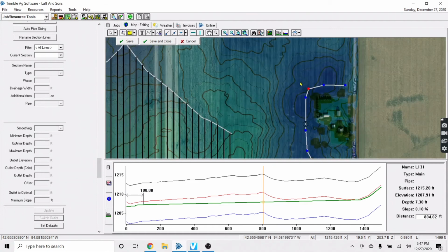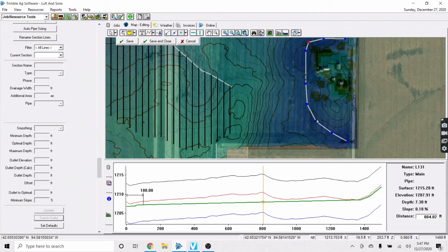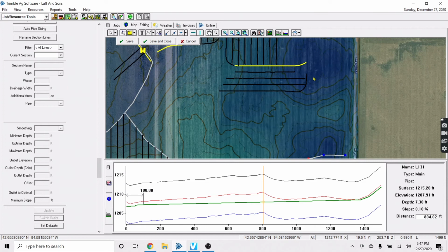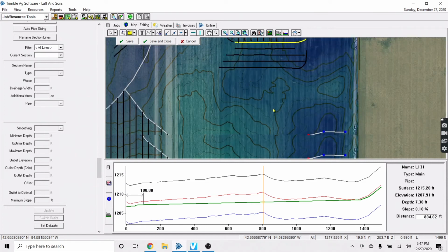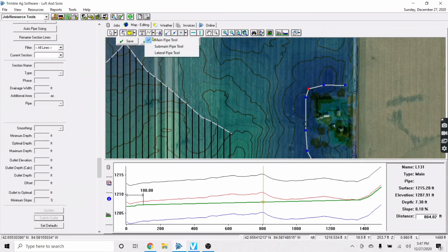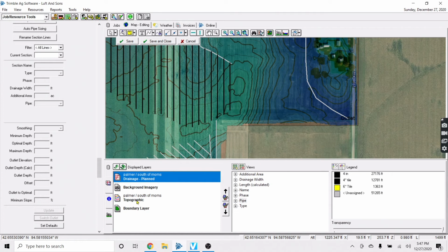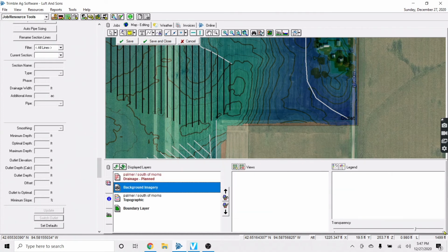Going to get 7 foot deep to get back there, which I think is the only way to go. Because if you go north, this being the lowest contour, 1, 2, 3, that's 7 foot there too. We could go this direction, but you'd be just as deep, and you'd be running 2 lines instead of just 1. Probably leave it the way we got it.